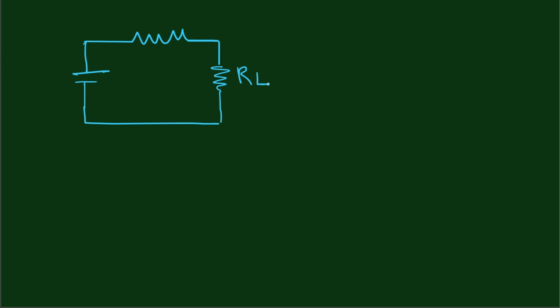And now we have to draw our Thevenin's equivalent circuit. Now we have to connect our load resistance, which will be 160 ohms. RL is 160 ohms, VTH which was 85 volts, and RTH which is 10 ohms.